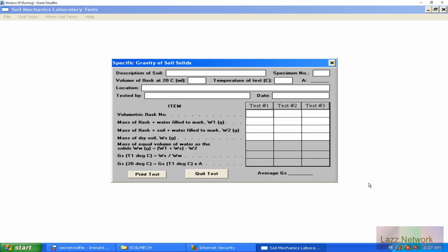so that's why, depending on the method, which granted for both of those test methods, it does indicate if you're dealing with peat-like material or organic soils, you want to probably try to do it that way instead of oven drying it in a 230 degree oven, or 110 degrees Celsius oven, 230 degrees Fahrenheit.